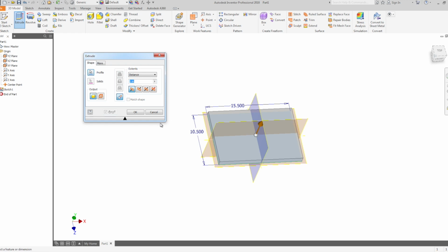And now it's going to automatically detect there's a sketch there, and it's going to want to extrude. Extrude just means pulling that two-dimensional shape out and expanding it outwards. And we're going to do this, which is the thickness of the laptop chassis, which we measured as 0.75. I think it was a little under 0.75, but we'll just do 0.75. It doesn't have to be exact.